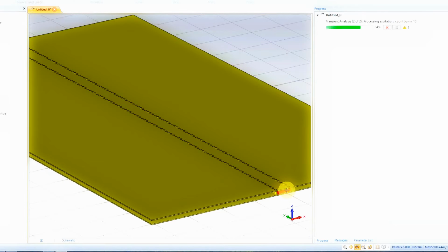The transient solver works by putting in a signal at the front and listening and seeing how it comes out at the end and at the front again if there are any reflections. It does a numerical technique based on Maxwell's equations, and it waits for the signal to die down past a certain threshold. So that option that we had, accuracy minus 30 dBs, it waits until the signal in all the cells is 30 dBs lower than the amount of energy that you put in the front in the beginning. And with a cutoff, if you simulate over cutoff, then this stuff just bounces back and forward.